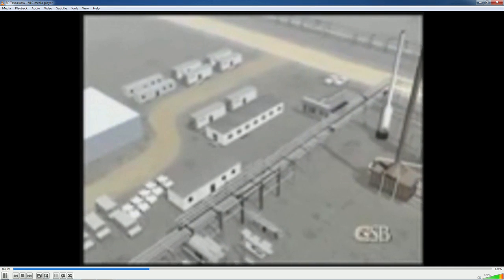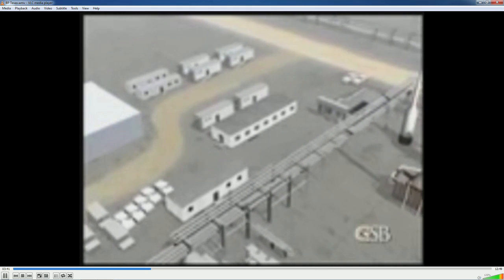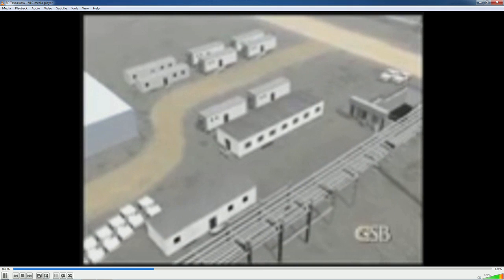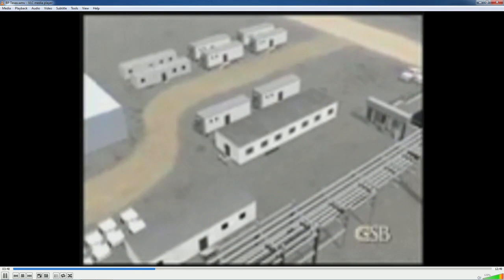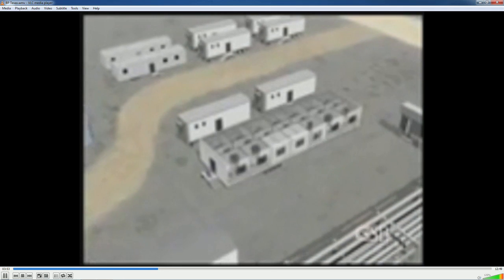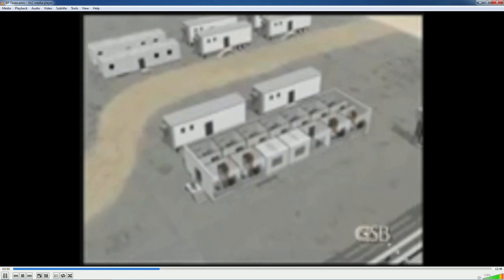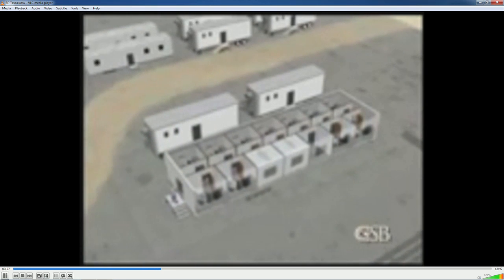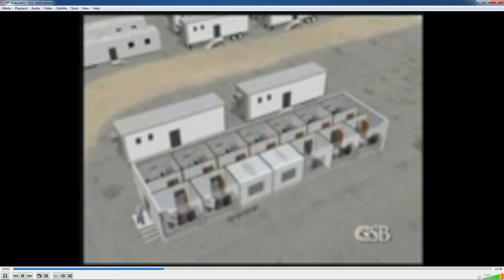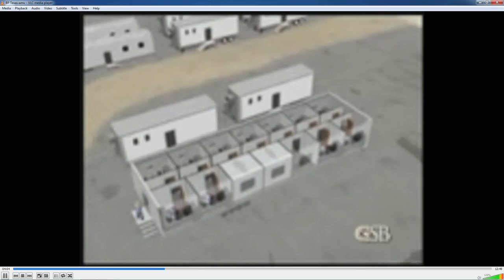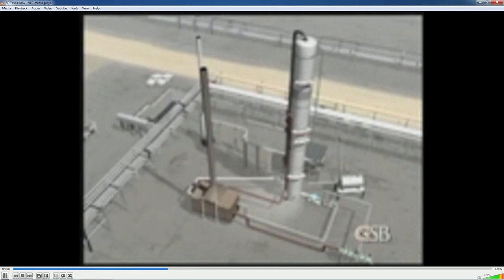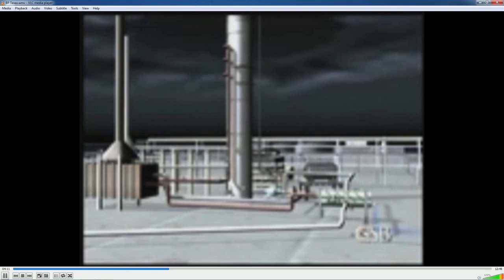BP had positioned a number of portable trailers close to process units for the use of contractors and other maintenance workers. Over a period of months, BP had located 10 trailers for workers servicing the ultra-cracker unit, including a double-wide wood frame trailer that contained 11 offices and was regularly used for meetings. Though these trailers were located near the isomerization unit, the occupants were not warned the ISOM unit was about to start up, a potentially hazardous operation.